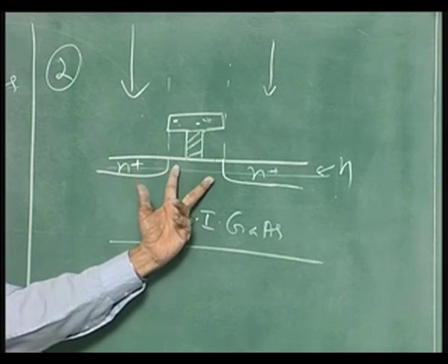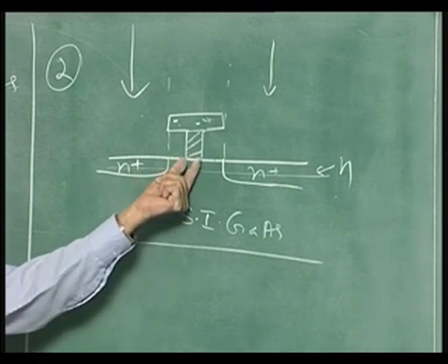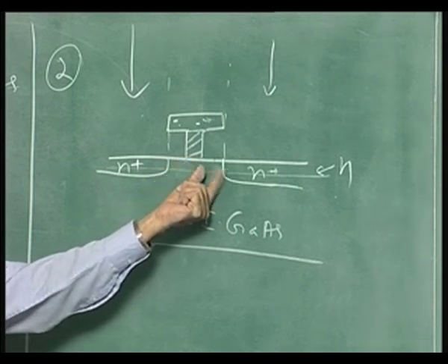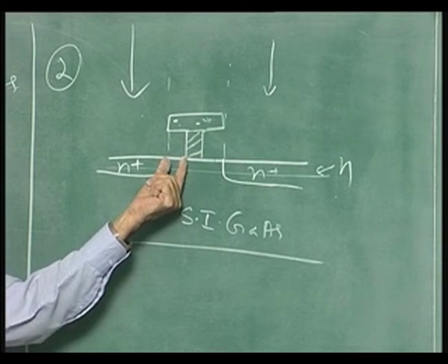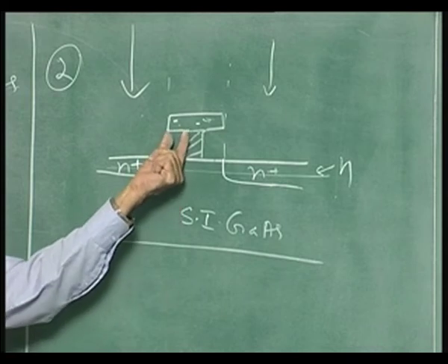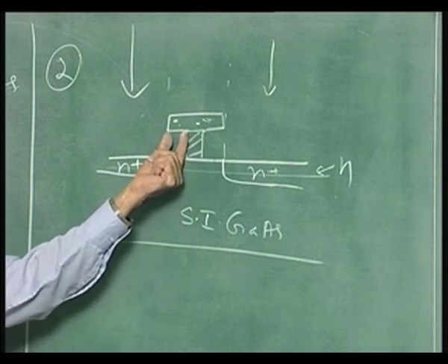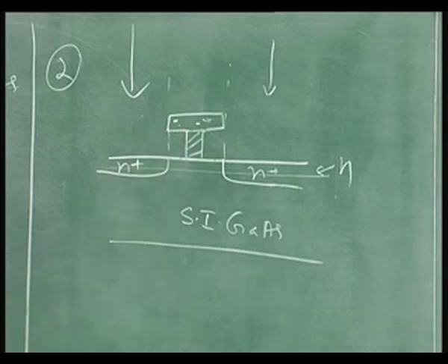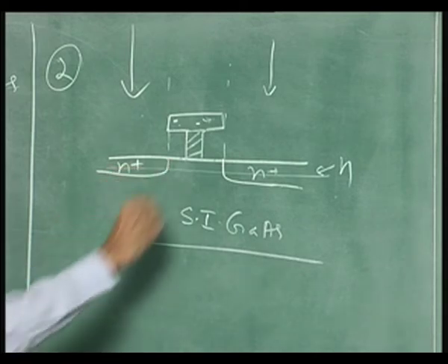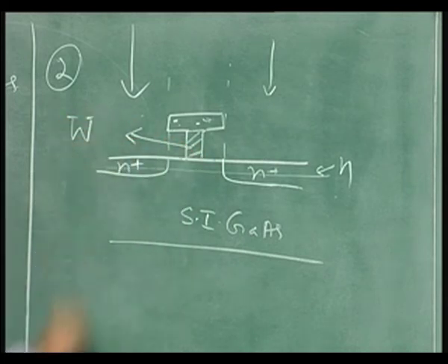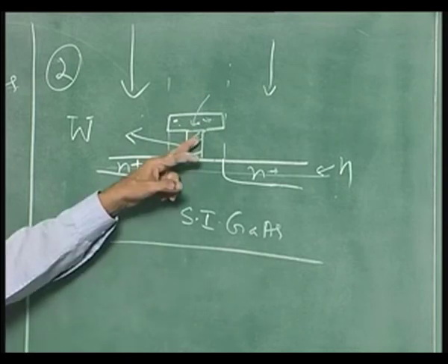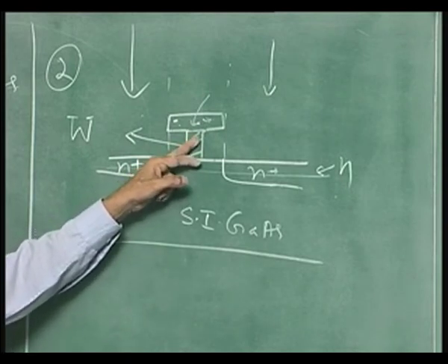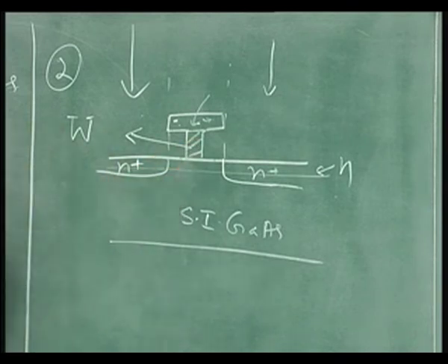This is self aligned. But where is the gate? Here. There is a gap between the gate and this drain contact. You can make this as small as you like, 0.1 microns, 0.2 microns, by adjusting this. Okay. So, you can get close to self aligned structures here. The only problem here is, in fact, people have made not only devices, but some integrated circuits also using this type of structure. The problem is, this has got to be tungsten, W is tungsten, tungsten titanium alloy. Okay. And this particular layer on the top, that can be a photoresist which does not get attacked during the etching of this one. So, how is it made?